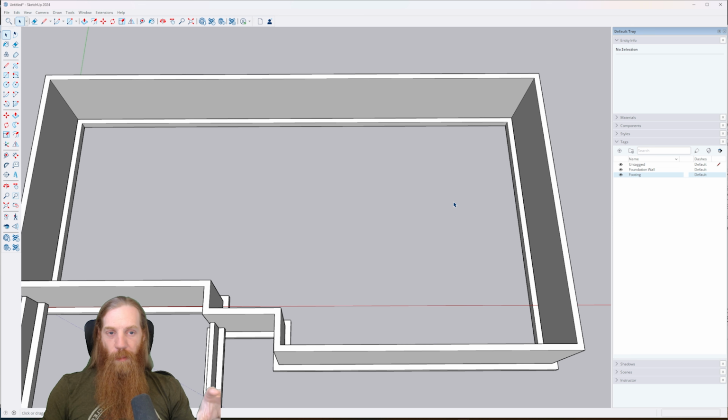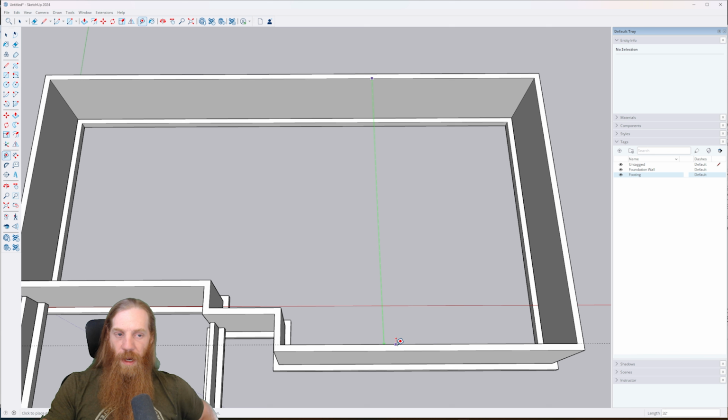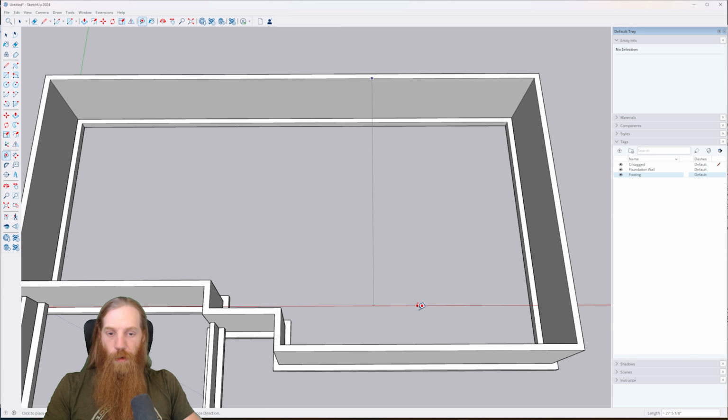it could be center of the floor joist, or it might be the ends of the floor joist. But especially with a basement that goes this far across, you could span this entire basement using probably like floor trusses, right? What is that, 32 feet? Yeah, you could do a 32-foot floor truss. It'd probably be a 24-inch truss. You could span the whole thing with that, and then you wouldn't have any load-bearing walls on the interior. It's a pretty expensive way to go about flooring this home. So the cheaper way to do it, you pour a couple interior footings, you build some load-bearing walls on top of that that will go across this way, probably one like right there, and then you could do one right about there, right?